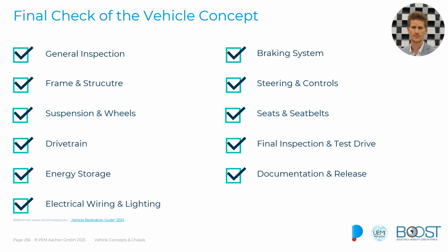Is the battery charging properly? Is it giving the full power you actually need? Check the electrical wiring and lighting. Go through it one by one and check if everything is fine. Check the brake system. So we mentioned that during the brake part, that is the most crucial safety feature. So please make sure that you brake the car or brake the vehicle test-wise also under full load to see if the brakes withstand the full force.